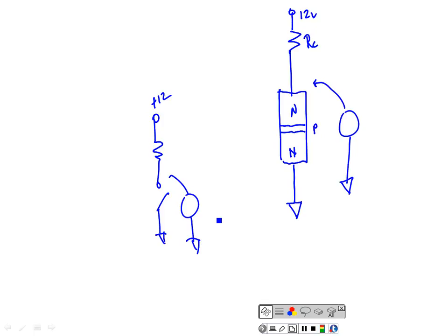Any open in a series, so to get the voltage drop across this resistor right here, V is equal to I times R. V would be equal to 0 times, let's say it's 1K, 0 times 1K. So what would the voltage drop be across that resistor? If that resistor is dropping 0 volts, that means I have 12 volts right there. Y'all understand that? So in a series circuit, if you got an open, the entire applied voltage appears across the open. Why?